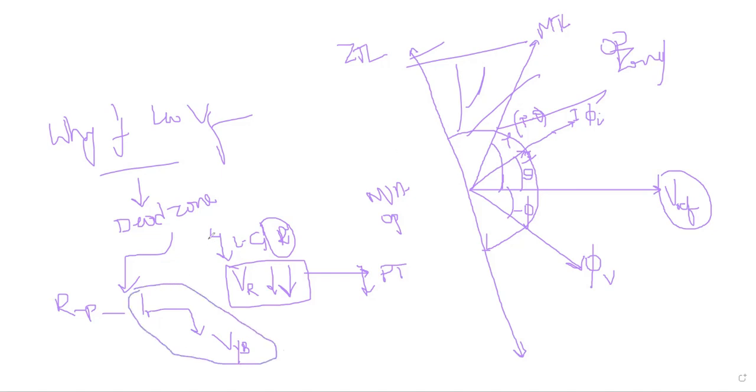Now again one question: if a three-phase fault occurred, then what would happen? If all the phases fault, all the voltages will collapse. In that case, our numerical relays will take the reference voltages from their pre-fault memory, team, where they had seen the voltage before, and it will do the action from the pre-fault memory. So this is about the directional overcurrent protection, team.